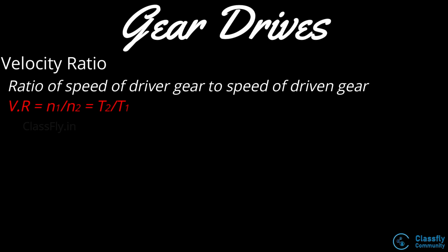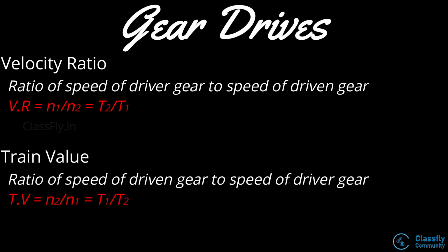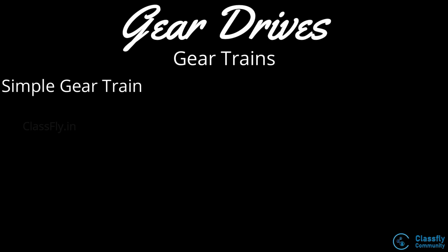Then we studied about velocity ratio, that is the ratio of the speed of the driver gear to the speed of the driven gear, and also the train value which is nothing but the reciprocal of velocity ratio.